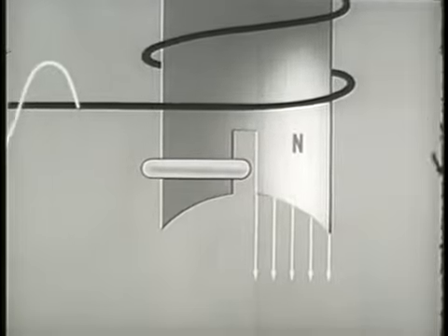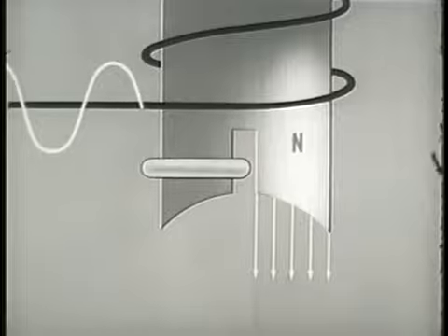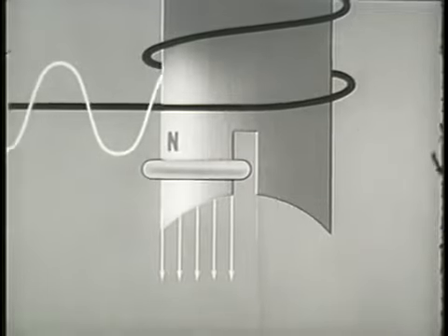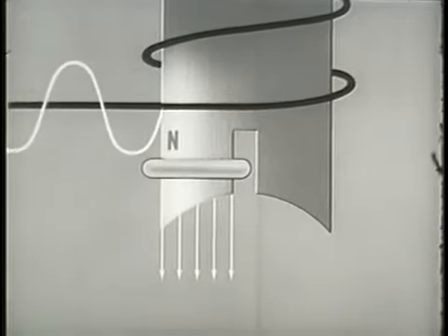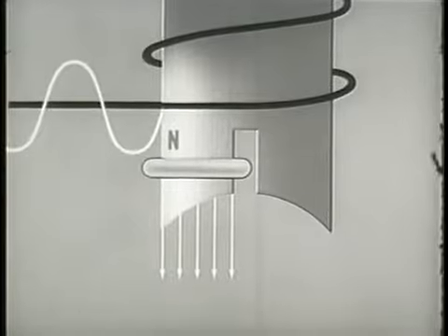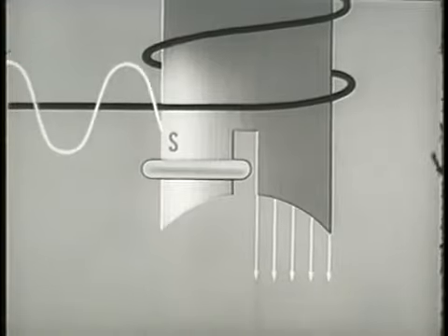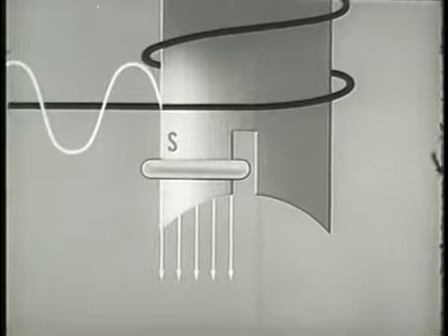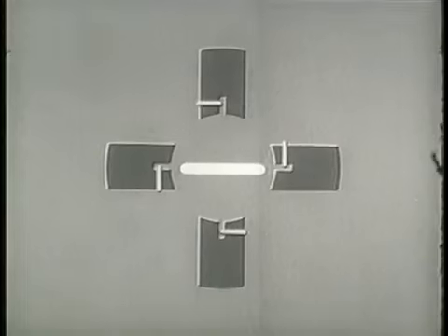Lines of force will emerge from this unshaded section of the pole face first. The inductance caused by the ring makes the shaded portion of the pole lag behind. This alternating pulsating action creates a phase difference within the pole. Let us see now how the use of shaded poles actually produce a torque or turning force in a single-phase induction motor.